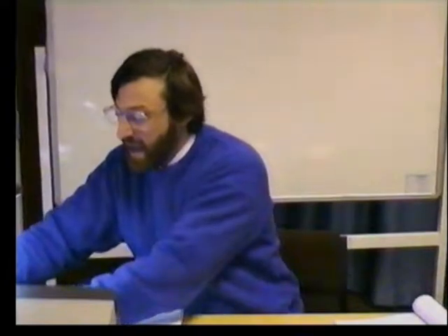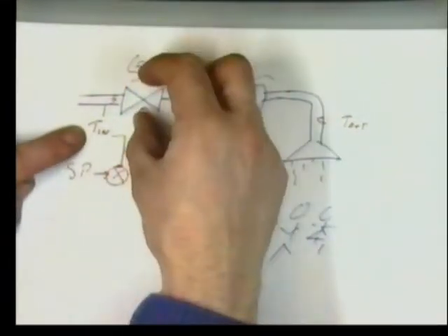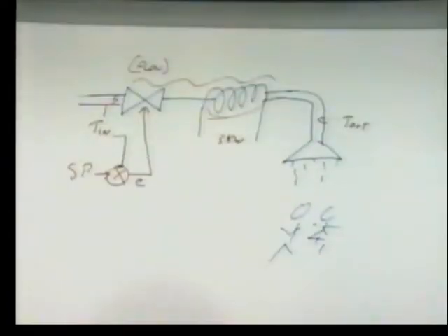We know mathematically everything about our control system. We know the heating element, how efficient it is. We know the volume of the pipes. We know the specific heat of water. Given these pure physical constants, we know precisely how many degrees C the water will rise from the input temperature to achieve the set point dependent upon a certain flow rate.